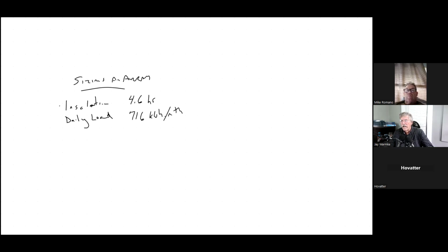Well, hours of insolation, divide that by hours of insolation, but that's insolation per day. So when I need to know what's my daily load, I'll take that 716, and then I usually divide it by 30.5 days in a month. So that in this case is going to give us 23.475 kilowatt hours per day.